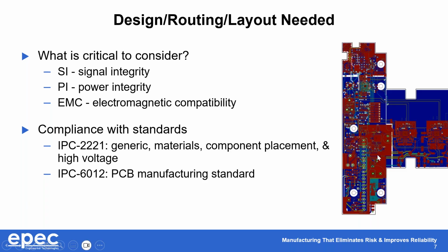And over here you can see a completed PCB with a split plane and some intricate cutouts. So if you had told us that this board was 4 inches square, but all this was missing, we could potentially route into this area and lay out. So knowing the exact dimensions of a board and what that profile looks like is critical.